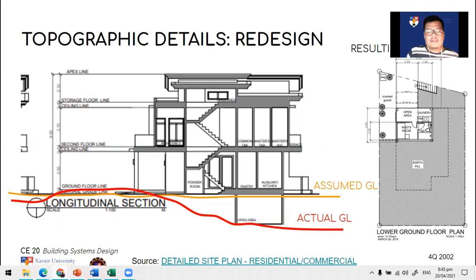The first proposal was to excavate soil. So I had to go to the site and check on what's the profile of the soil. Since we are limited with surface level instrumentation, that means that we need to gather the geologic profile of the soil. We noticed that there are big chunks of rock, and we're worried that once we dig into the soil, this rock is quite big that we could no longer remove it from the surface.